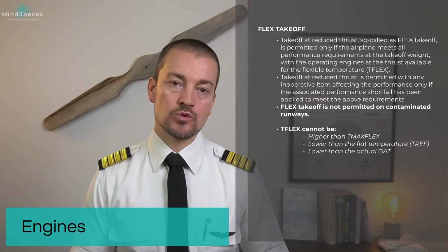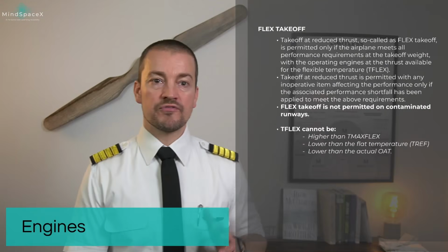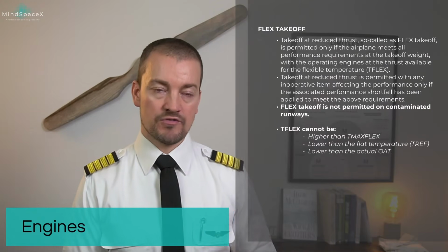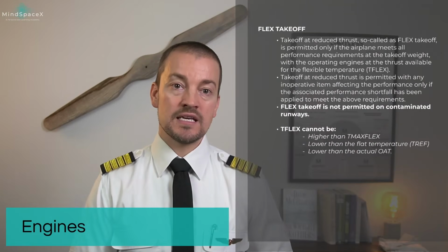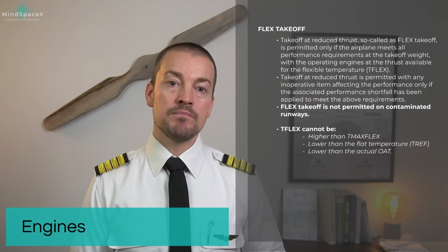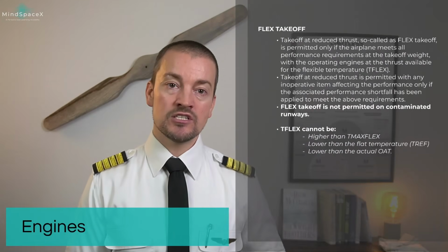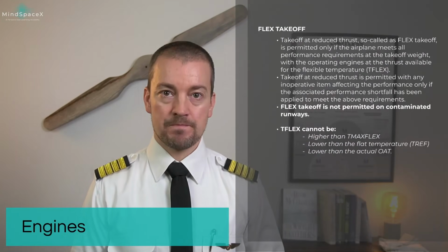In the performance presentation, we talked about the use of flexible temperature for takeoff. This was a way to optimize the takeoff and minimize the wear and tear on the engine, prolonging the engine's life.